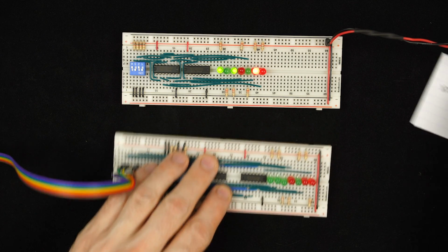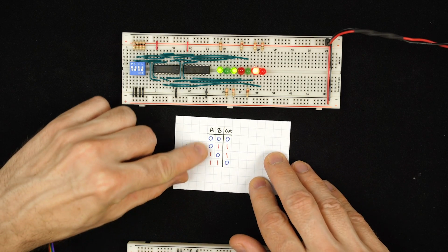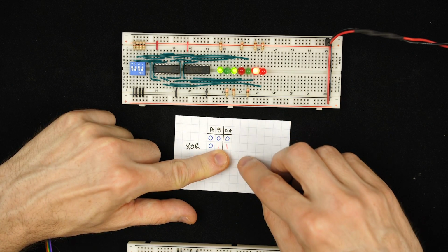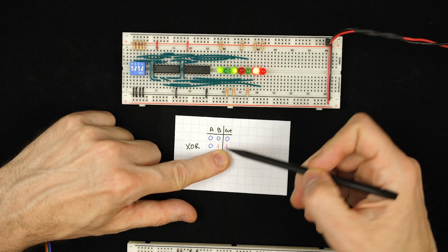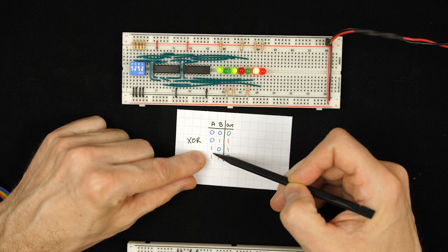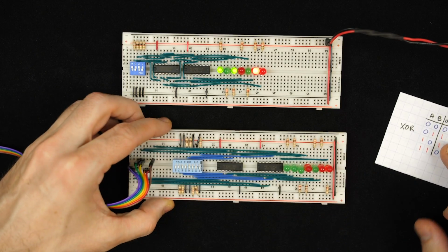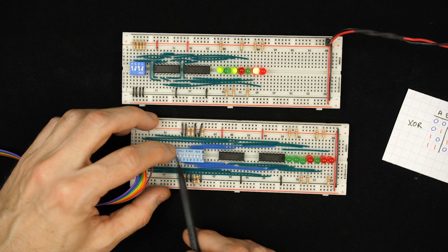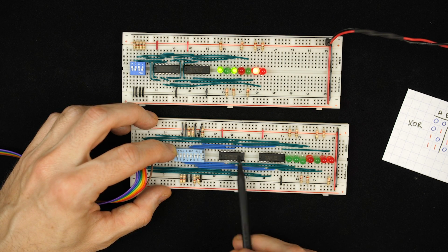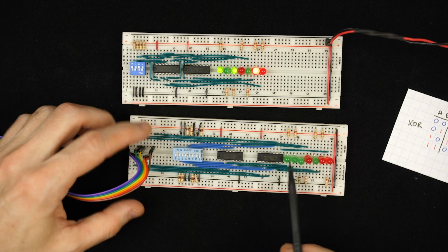And the way that an XOR gate works, if you look at it, is if one input is off, so let's just look at the top half here where the A input, both of those are 0, well, you can see the output just follows whatever the B input is. But if we toggle that first input on, then you can see the output is the opposite of whatever B is. And so that's basically what I'm doing here: I've got an XOR gate where the A input you can think of as these dip switches. If they're all off, then the output of the XOR gate is going to be whatever the input is. So I've got 7 inputs here, I've got 7 outputs. The outputs are going to be the same as the input.